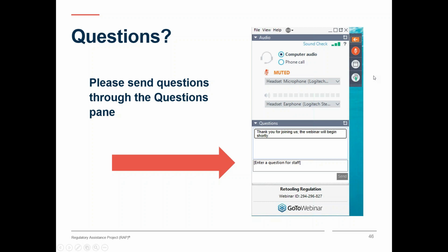Thanks, Jim. I will offer an answer on the second part of the question that somebody asked. While there's probably not an indisputable way to split the cost of AMI, one thing you can do is allocate it in proportion to the benefits of AMI. If you're saving on meter reading, you allocate part of the cost to meter reading, and if you're saving on peak demand or energy losses, then you allocate it in the relevant proportions of those three benefits. So that offers one principle for splitting up the costs.